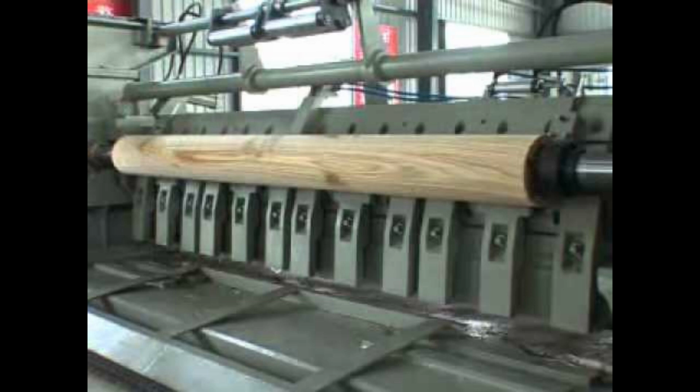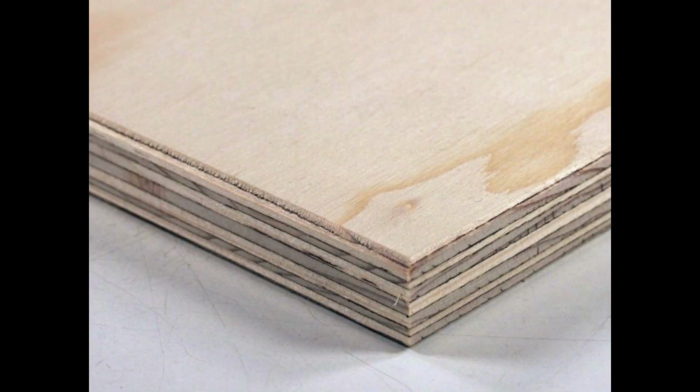A typical plywood panel has face veneers of a higher grade than the core veneers. The principal function of the core layers is to increase the separation between the outer layers where the bending stresses are highest, thus increasing the panel's resistance to bending. As a result, thicker panels can span greater distances under the same loads.